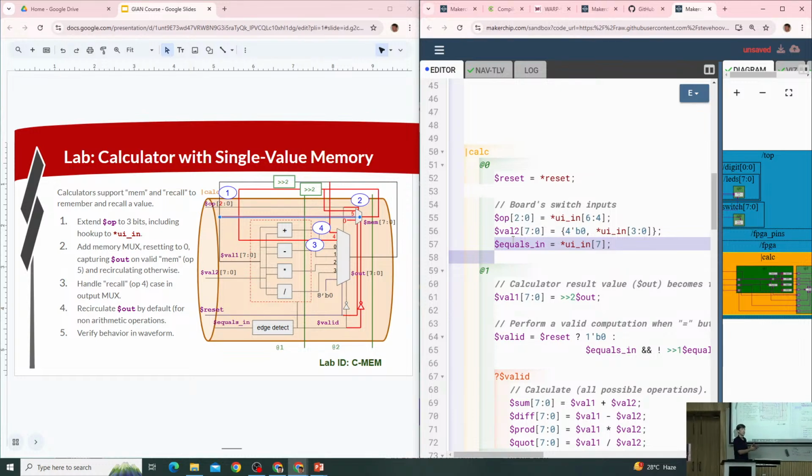It's not necessarily arriving consistently. So when you distribute an asynchronous reset and then a clock comes along, some places see that reset, some places don't. And there's no guarantee that you're going to see it the same every time. So there isn't one reset flow. It can happen differently in different places, and there's no way to verify all those combinations. If you create a synchronous reset in one place and distribute that everywhere consistently, there's only one reset sequence.